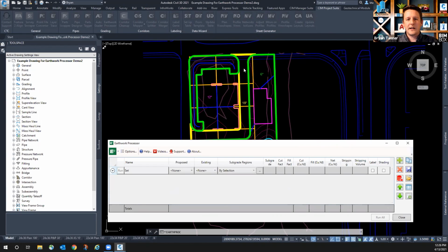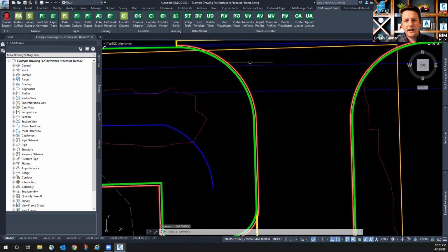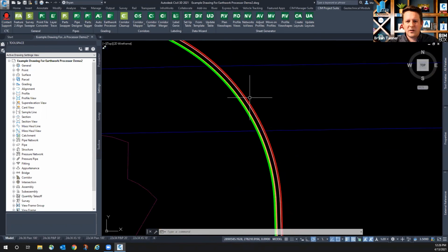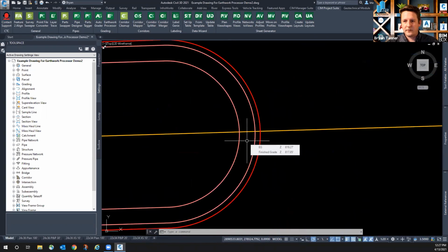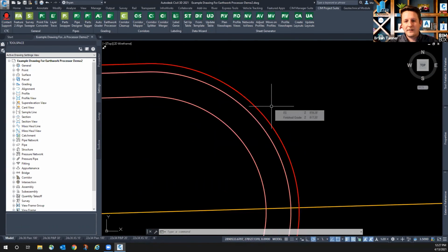And the reason being is the curvature. I'll jump back into this tool because this is a really important question. As we have that curvature around a parking lot or a roadway for that matter, or parking islands, and we have those mid-ordinate distances, those chords of our triangulated surface that cuts across these arcs of our surface definition, we need to make sure that those don't overlap. That's the big thing for me. So I end up typically, I know I used a 1/100th when defining my boundaries earlier.